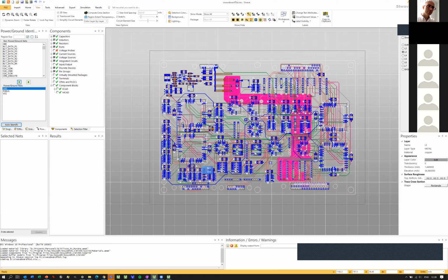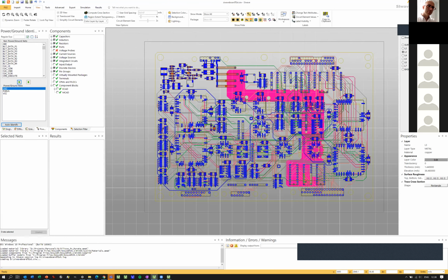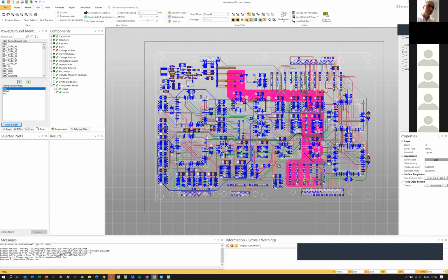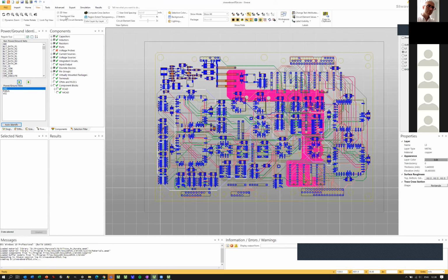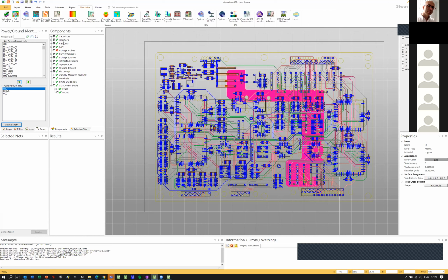So what we can do with the circuit boards with this is the SIwave. Basically, we can simulate a lot of different features. We can simulate how the current is spreading on top of the circuit boards. We can calculate electromigration, SYZ parameters, resonances. We can do frequency sweep analysis.